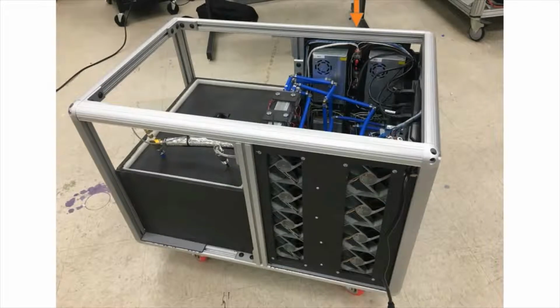This side of our project contains our 4 power supplies. Each power supply is able to deliver up to 30 amps at 12 volts. The relatively high amperage was necessary as each of our Peltiers is rated to draw up to 10 amps of current. This meant that we had to split the Peltiers up into 4 arrays, each of which had to draw less than 30 amps. 3 of the power supplies contain their own 3 Peltier arrays. The 4th power supply energizes the final Peltier along with the proportional valves, compact Rio, and pumps.